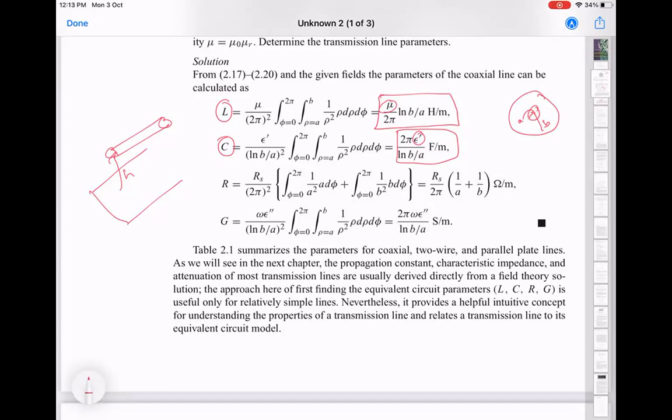So just to summarize, the connection between the geometry and the inductance per unit length and capacitance per unit length comes by connecting the idea of electromagnetic energy present in a section of a transmission line, computed from the fields, for which you need to solve Maxwell's equations for a particular geometry, and then equating it to the telegrapher's model of the transmission line and writing it as L i squared and C v squared. From equating those two, you will get these L's and C's.